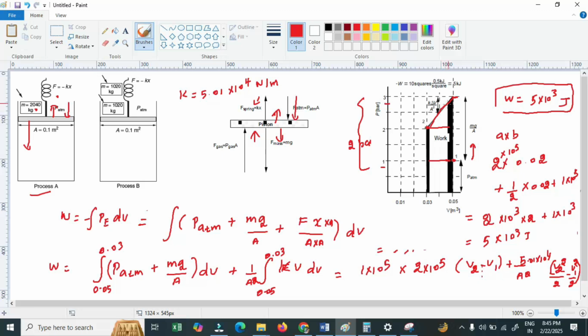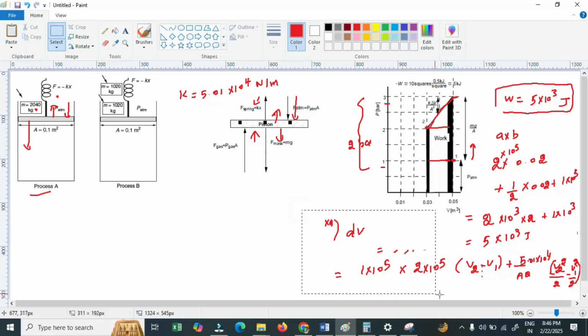And if you want to know why it is the inclined line, we can do other check also. I will do that also here. So now this plot is nothing but the plot between the P and V. So the moment the pressure reaches from here, the spring pulls down the pressure by expanding. So what is the pressure due to the spring?